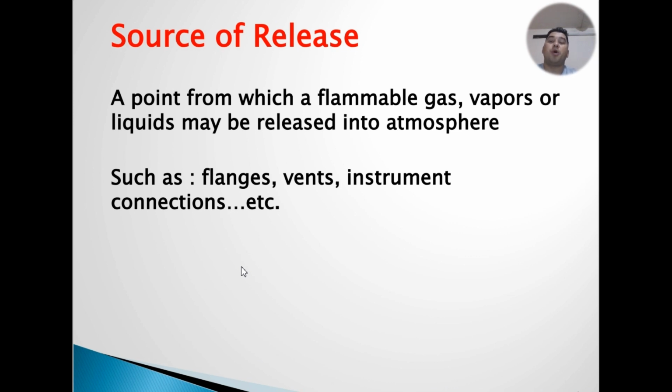Source of release: a point from which a flammable gas, vapor, or liquid may be released into the atmosphere. That we call a source of release, such as flanges, vents, instruments, connections, etc. From these things, any gas or vapor can be released into the atmosphere.